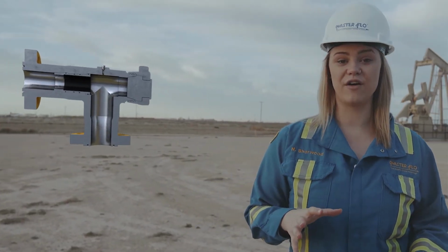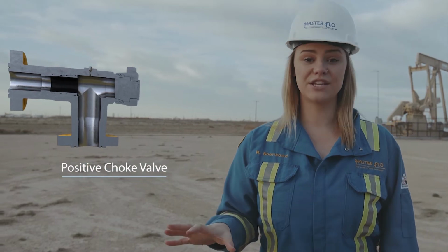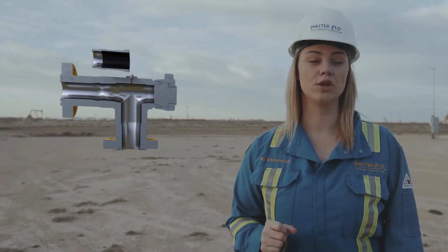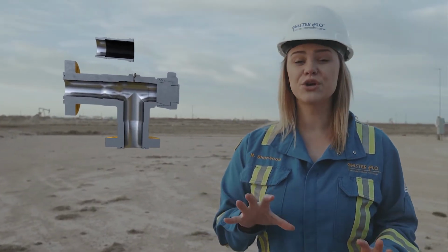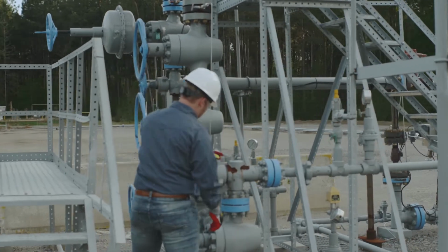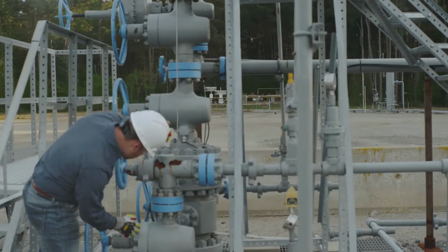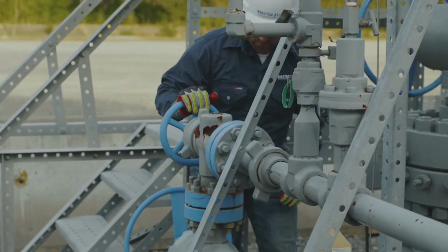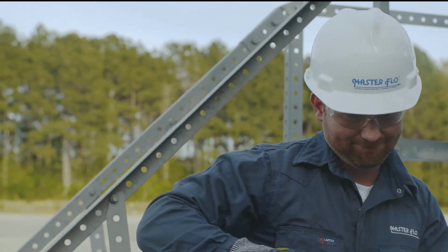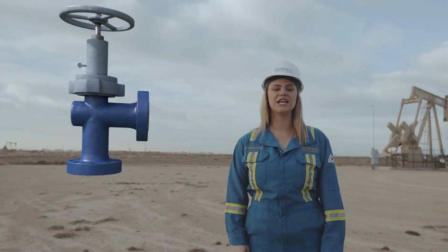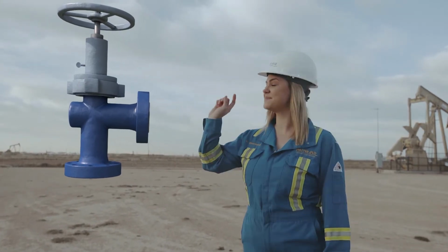The simplest choke valve is the positive type. The positive chokes contain built-in orifices called beans. To reduce erosion, these beans are often lined with tungsten carbide. However, these chokes are still susceptible to high rates of erosion. An adjustable choke can compensate for some degree of wear, but a positive choke cannot. The pressure must be isolated so that the valve body can be opened and the bean removed. This is time-consuming and expensive. For frequent flow regulation, an adjustable choke will work the best.